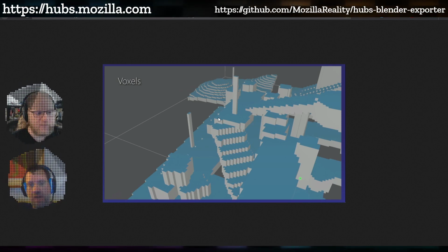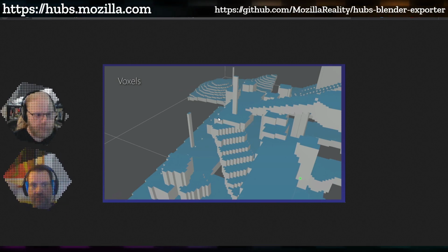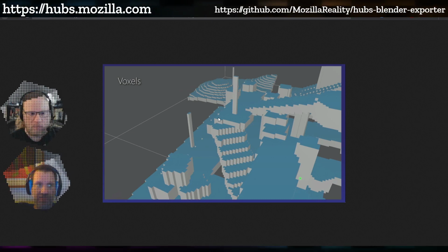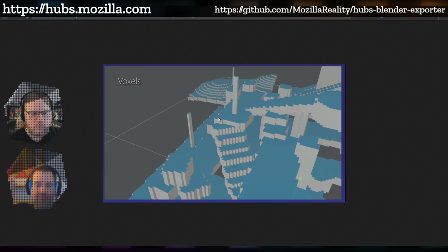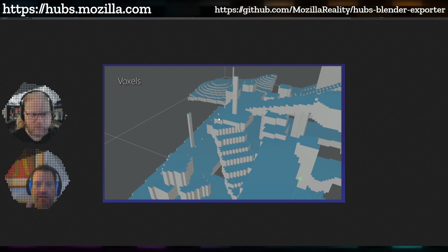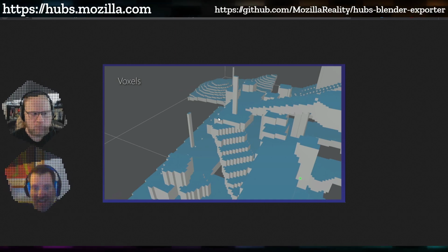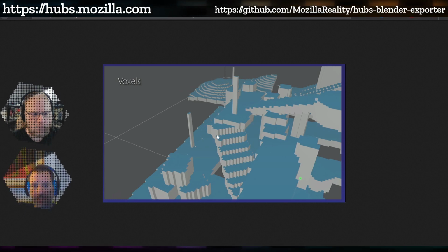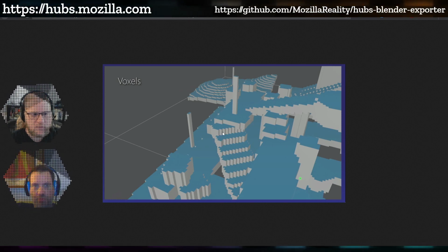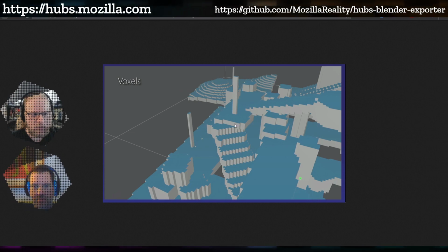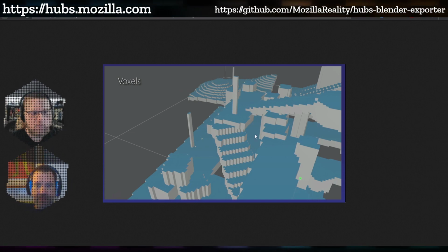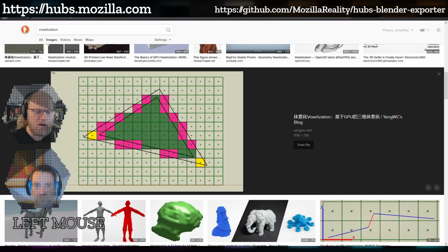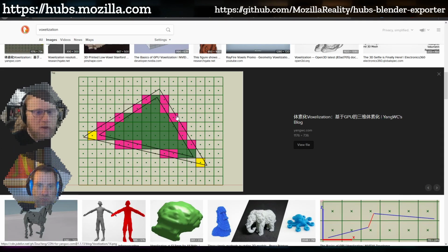I would say the biggest flaw with voxelizing a scene is that when you have primitives and shapes that are not facing cardinal directions, in other words, not north, south, east, west, but on diagonals, like these steps in this picture, there's a higher likelihood that a step will fall outside of a voxel. So it'll get cut off, and it's definitely an approximation.